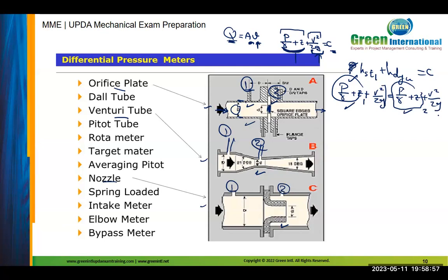So I need a supporting equation to get a relation between velocity 1 and velocity 2, to substitute into this equation. What is the supporting equation? We can use Q. So we can use Q1 equal Q2, continuity, conservation of mass. So Q1 is A1 V1 equal A2 V2.